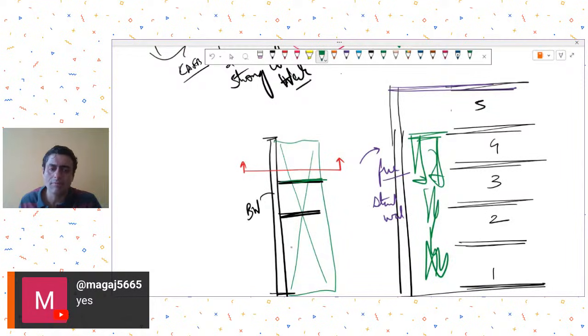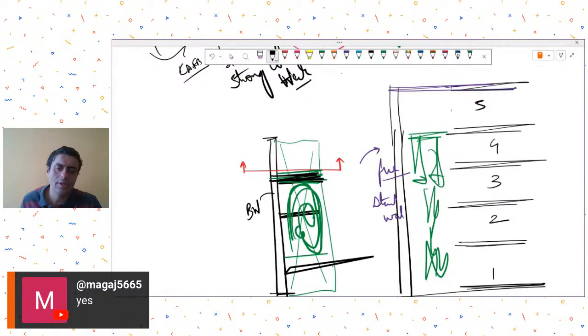If you are having ramps, let's say your ramps are circulating like this, you can get ties at mid landing level at least. I don't have your architectural plan in front of me, but assuming your ramp circulation is in this direction, maybe at mid landing levels you can always introduce ties. So at least one tie you get over here at one level, and one tie over here. Okay, so that is one possibility.